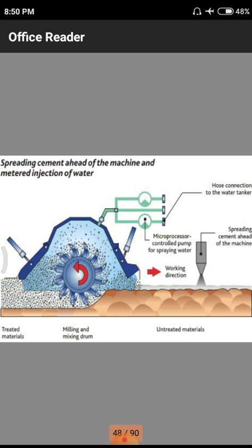In lime stabilization, we spread and mix the sample, and after that rolling is necessary. But in this case, there is spreading, mixing and rolling, and then watering also.